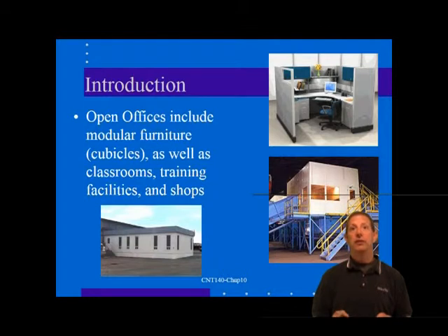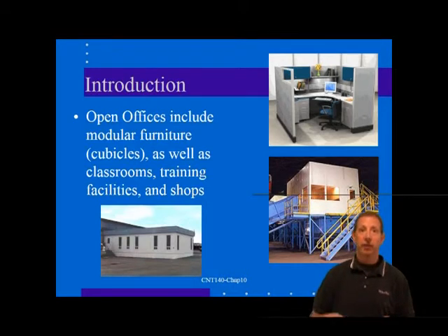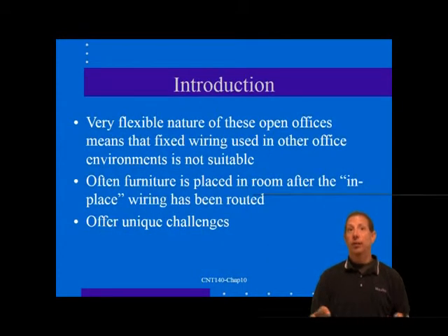Modular furniture systems typically place power and communication cables in narrow pathways within the panels of the modules, like the example shown here. These modules must be fully assembled before the cable can be inserted, which makes the process of providing home-run cables to the telecommunications room more cumbersome. This means that portions of the data and telephone cabling process must be postponed until the modular furniture has been assembled. At this stage in an office build-out, the ceiling tiles are already in, the walls are finished, carpet is laid, and the modular furniture is all over the place.